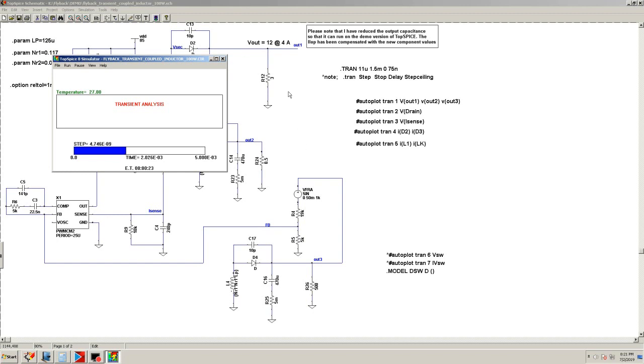And this is one of the disadvantages, that if you have uneven power or currents, the flyback doesn't regulate as well, or cross regulation is not as good. And in fact, you may have to put more load here to make it regulate better.